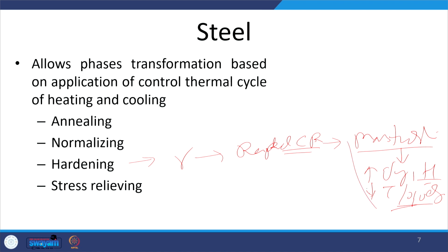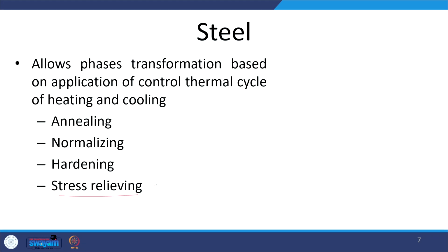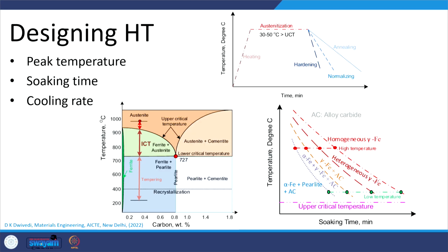Okay. So, the weld joints in hardened condition will not be used because of the reduced toughness and ductility. So, it is followed by tempering, so that a suitable degree of toughness is induced and the residual stresses are relieved. Then we can also go just for stress relieving by choosing the suitable heating temperature, so that the desired reduction in the residual stress can be realized.